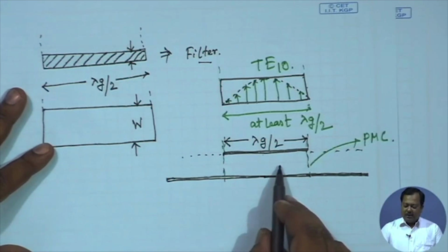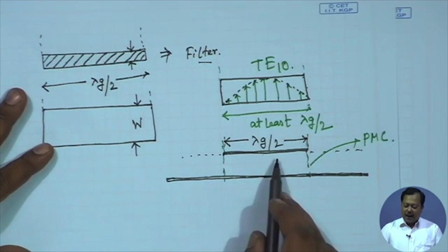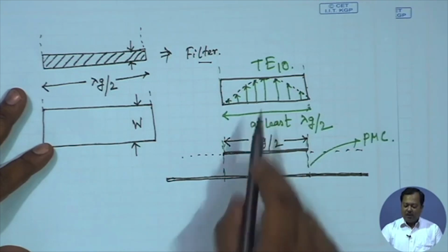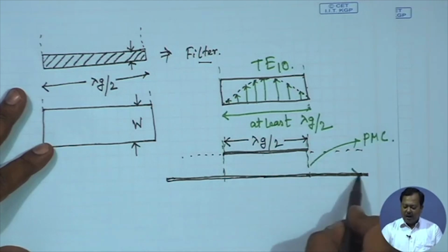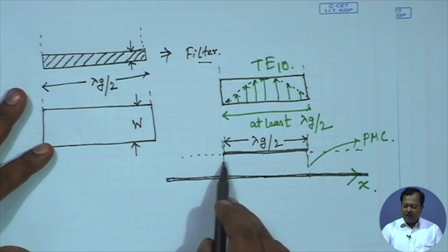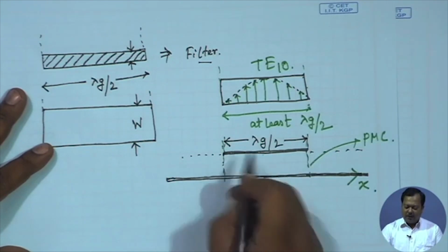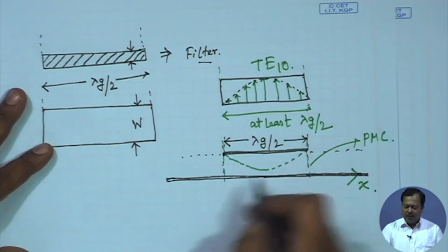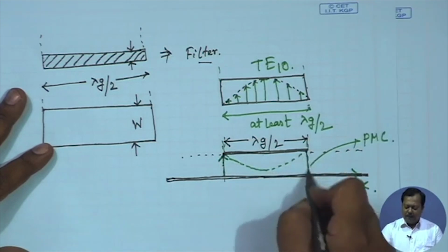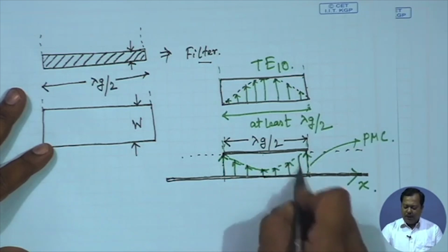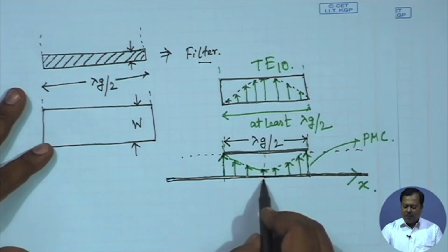So in this case, this microstrip line can support a transverse electromagnetic wave, but the variation of electric field along X will be different because we have open circuit at two sides. So how is the field configuration now? If I draw the field strength, it will be maximum at the two side walls where we have PMC, and it will be minimum on the central plane.